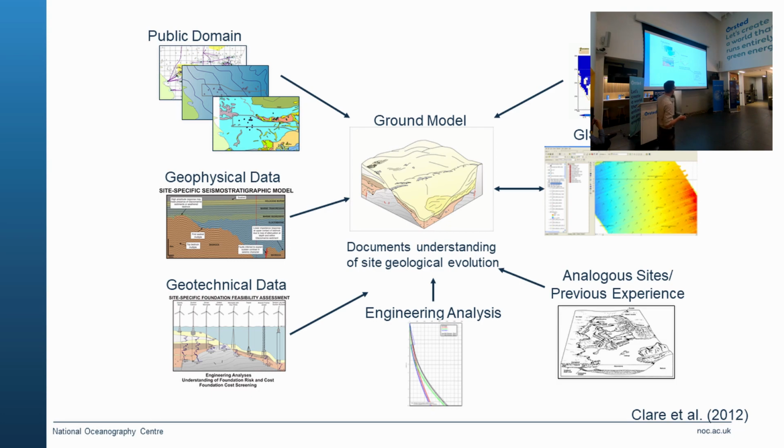One of the important points to note here, though, is it's worth having that communication early on in the project between geophysicists, geologists, and engineers, such that when horizons are being picked, they're not just picked because they're an easy, high impedance reflector to pick, but that they've actually been thought about. Might they represent an interface that could be geotechnically variable, so maybe a clay to sand interface, or a normally consolidated to an over-consolidated clay interface.